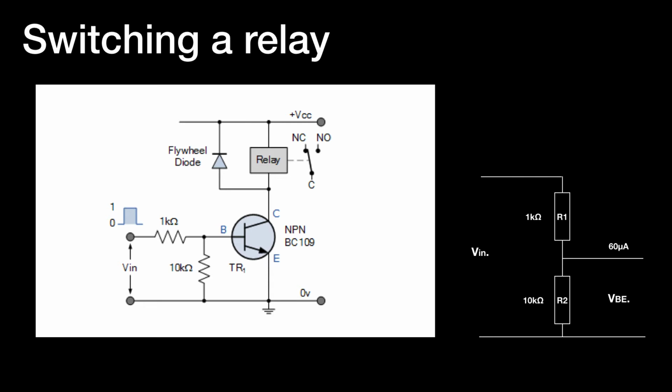So the voltage then on the base will be slightly less than the 2 volts applied because it's a potential divider. But it will forward bias the base emitter junction and current will flow. So if we had a pulsed waveform shown there with a 0 and a 1, maybe it's 0 and 1 volts, that would be sufficient perhaps, or 0 and 2 volts. And if that was coming in at V in as a signal,